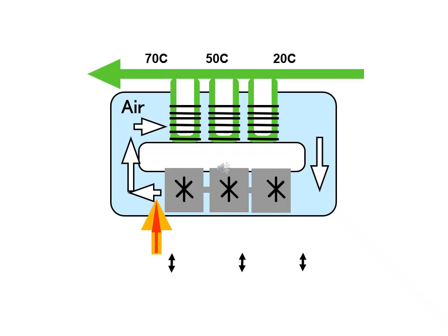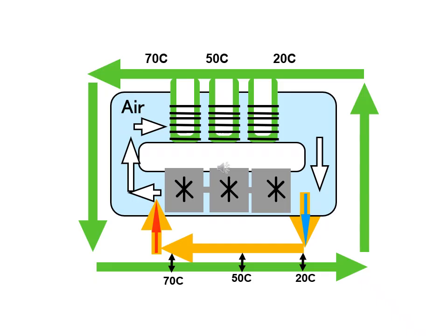The seawater exiting from the last evaporation chamber on the right side of the lower evaporation chamber exchanges heat with the circulating pure water shown in green and gets heated. As a result, the seawater gains the latent heat of condensation in heat recovery. However, there are concerns about heat loss, and that loss must be compensated by some heat source. This system functions economically utilizing solar heat and hot water storage even at night.